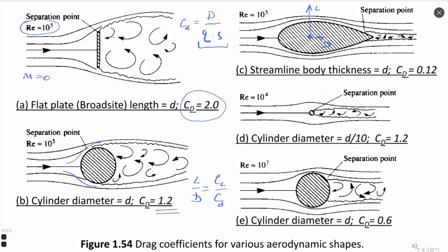We can see in case B, a cylinder of this diameter and an airfoil of the same thickness have approximately 10 times different losses or drag. This happens because the flow around the airfoil is smooth and does not create such a big area or volume of turbulence. So the turbulence area is small behind this airfoil.